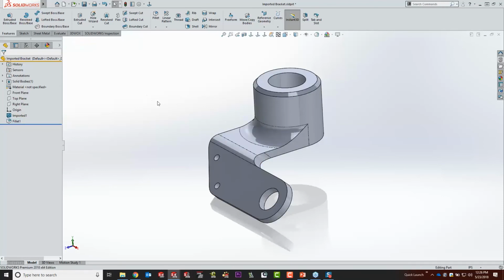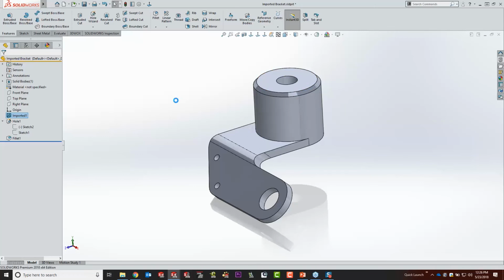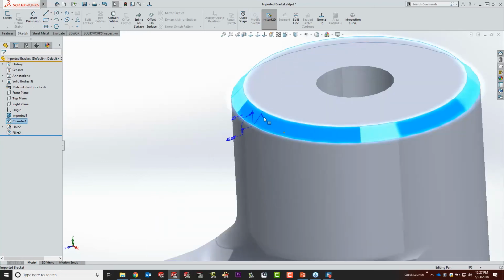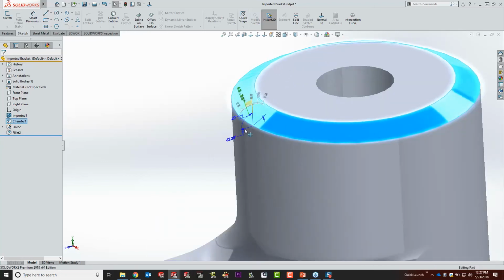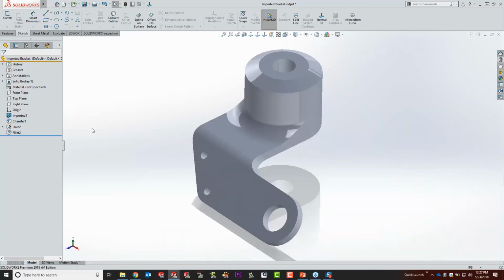Now with this feature that I've recognized, I can really go anywhere I want with this. I can pick on a hole and say Edit Feature. What that'll do is give me now, in this case, a hole that matches my hole wizard, because of the size being a standard hole, so that's a great thing. It's editable now, so I can modify that. And then this chamfer up here, which is just an edge on a part so far, but if I hit Edit Feature, you'll notice the feature that gets created in the tree for this one. So this one actually put a chamfer up above the hole, just based on the way feature history works, and gave me now an editable feature that we can modify the angle and definitely modify the distance of that quite easily. So I love FeatureWorks for what it does for simple changes to pretty much any part that's out there.